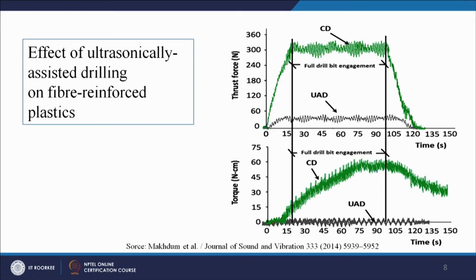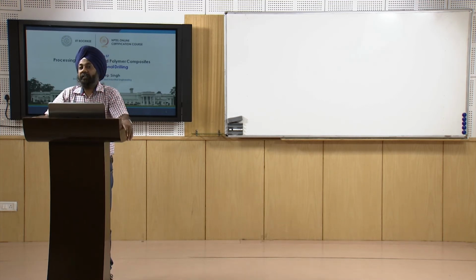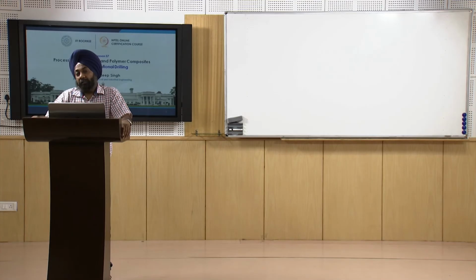So conventional drilling: more forces, higher magnitude of forces, more damage. Ultrasonically assisted drilling: less magnitude of forces, less damage. So very easily it can be concluded that if we use ultrasonically assisted drilling, our performance will be better.